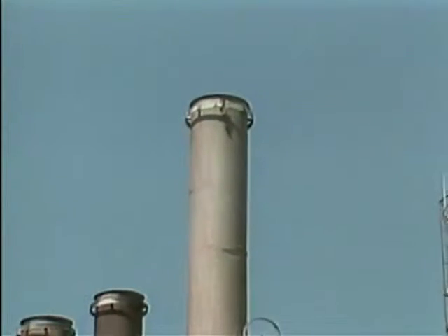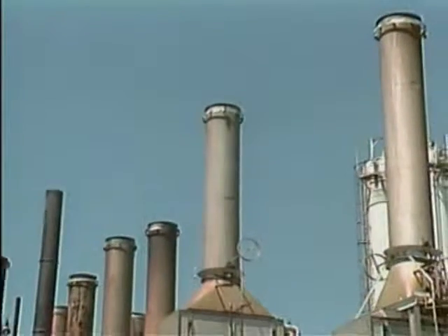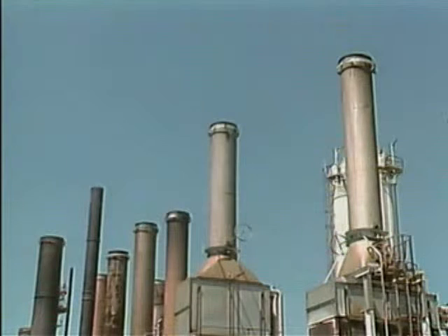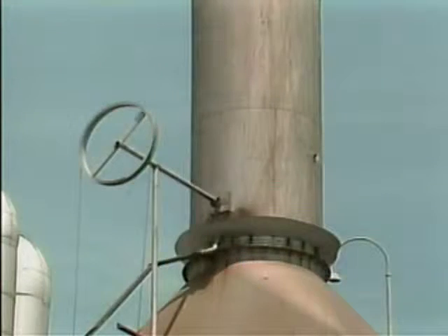In a natural draft furnace, the height of the stack affects the amount of draft that can be produced. In general, if all other airflow conditions are equal, the taller the stack, the greater the draft. This is because a taller stack creates a greater difference in pressure. Often, the amount of draft must be adjusted for proper operation of the furnace.